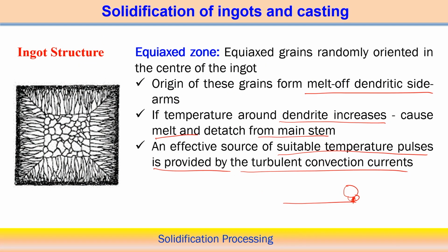in that equiaxed zone, nucleation occurs at the same time at several positions, and then the grains try to grow, with competitive growth. Here the gradient variation is not much, so the grains have almost equal chances to grow. In that situation, grains of more or less equal size are formed at the center part.